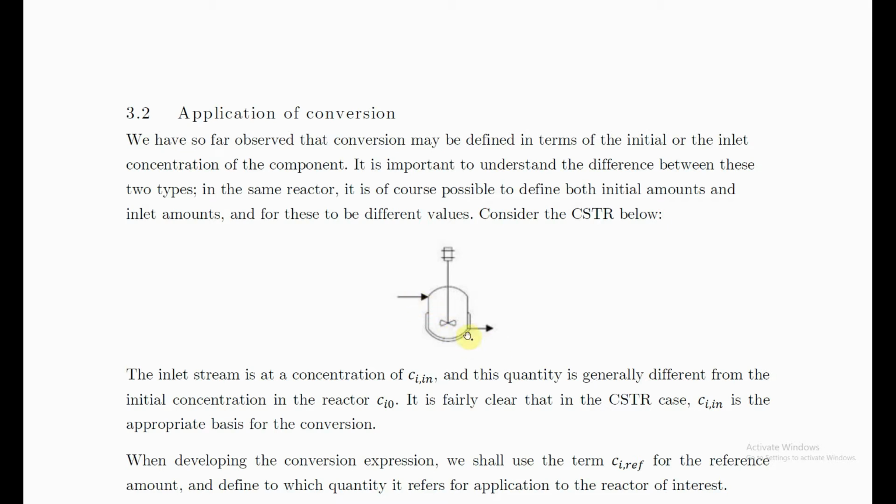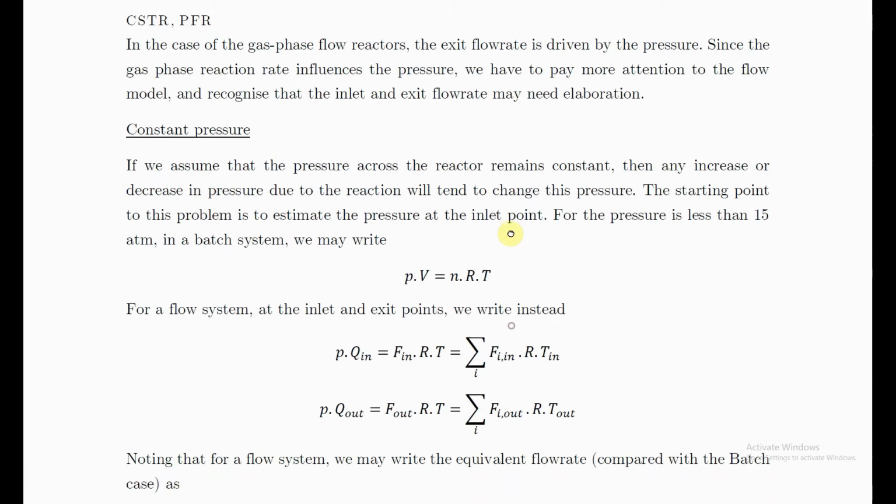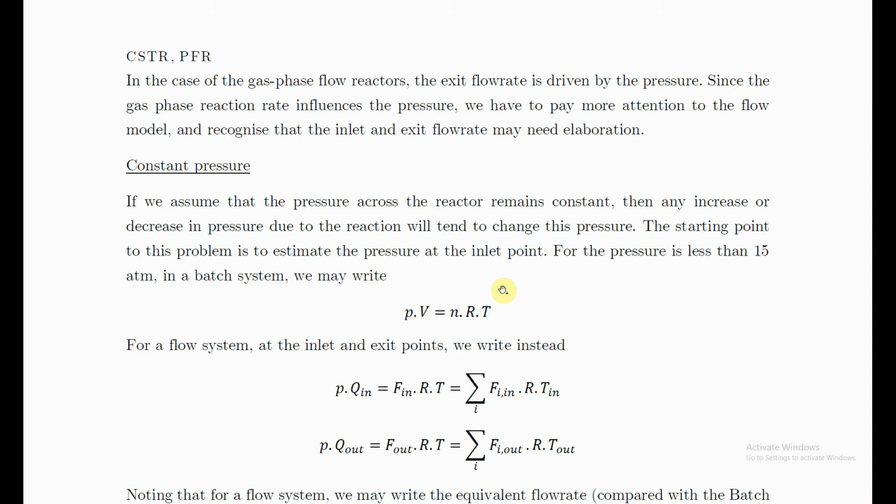So this is one of the assumptions that we could apply, and of course we can go and test that and so on. But generally, we know from our fluid mechanics that if we have an applied pressure, and if there's a lower pressure in one line compared with the other across the same space, then what tends to happen is that the pressure, or rather the flow rate, will change such that the pressure becomes the same. Right? So if the pressure becomes the same, then we can establish a relationship between the flow rates.